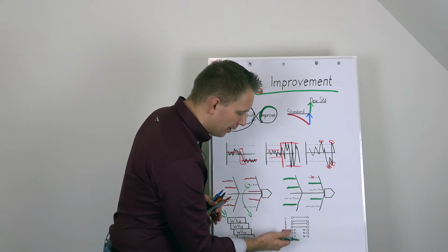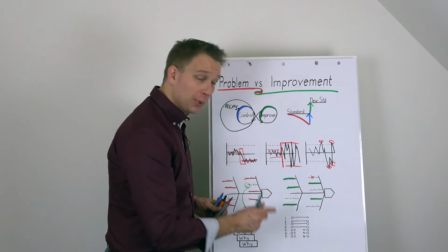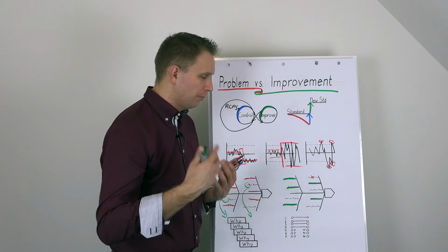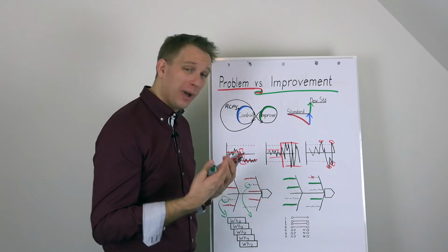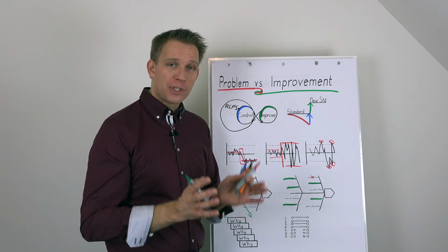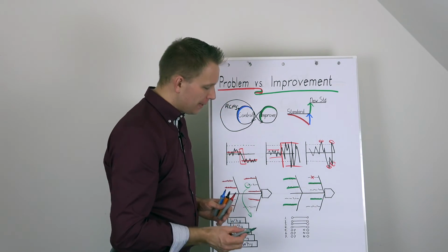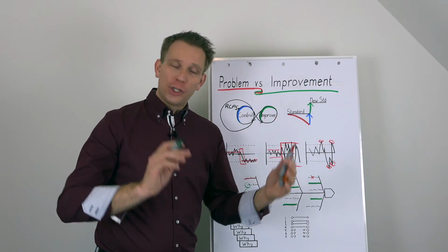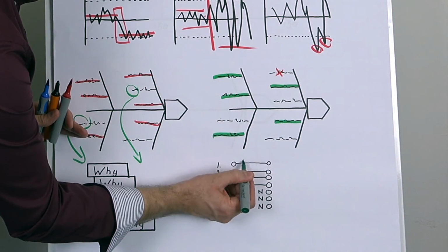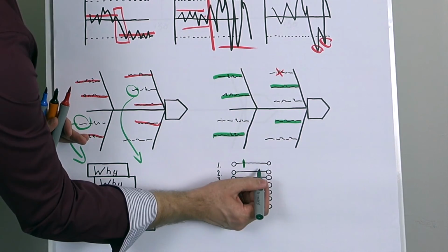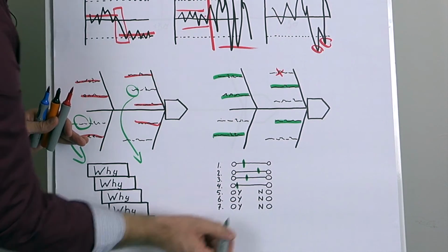And that's when you start making this list of parameters and settings for your process. So these are machine settings, but they are also material things. They are also how to do the maintenance. They're also how to load. The 4 M's are completely in scope, and you just list those parameters. And there will be some that are on a scale where your job basically afterwards is to say that was the ideal level. And for parameter 2, it's over there. And this one also over there. This one has to be very minimal.